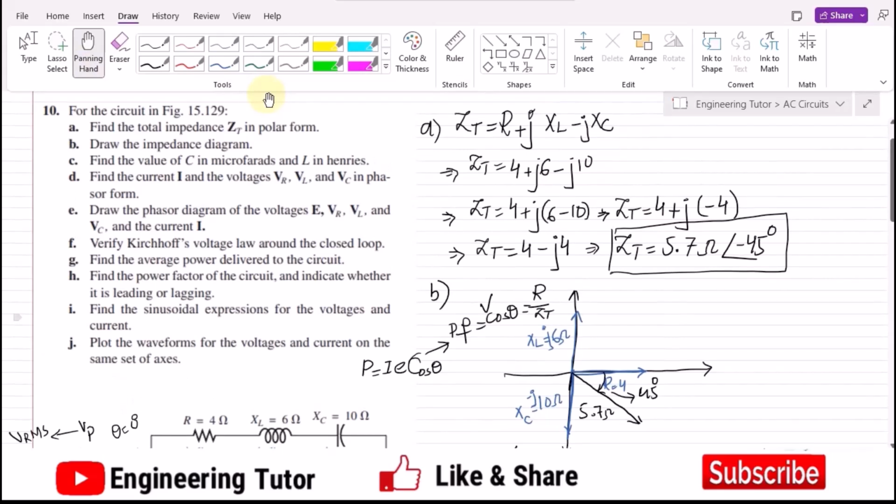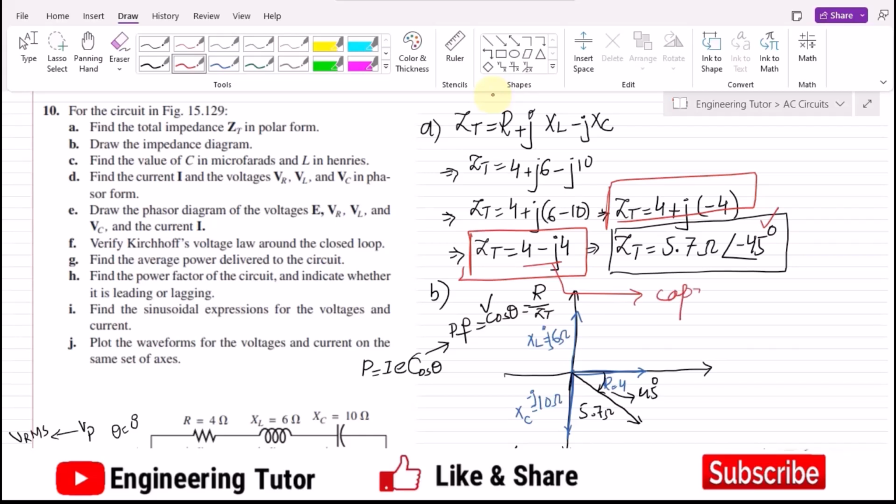So here in the diagram or in the impedance, we can very easily see that this is now a circuit of capacitive nature, because the capacitive reactance is dominant here due to the negative sign with the imaginary term, and also this negative angle.